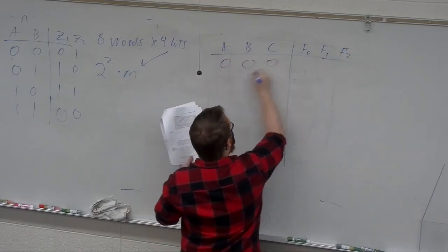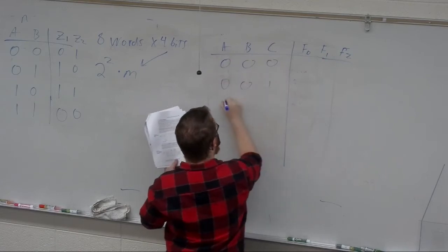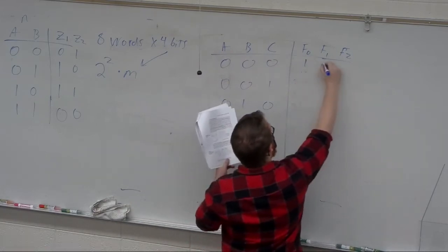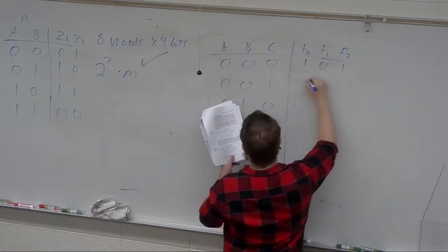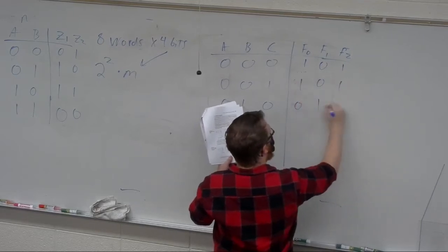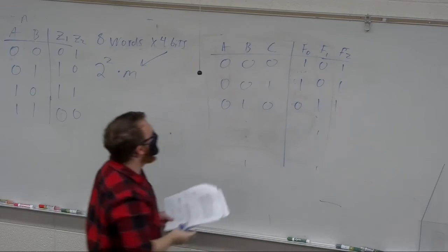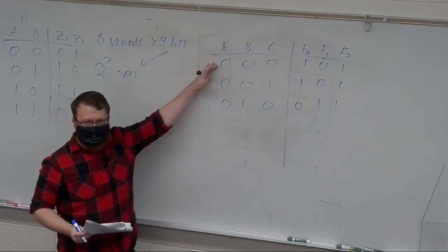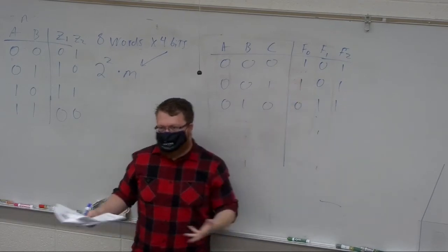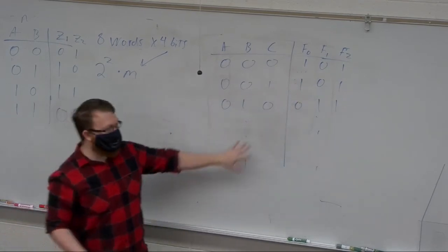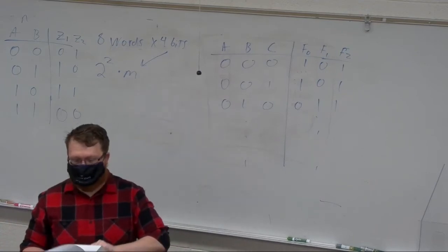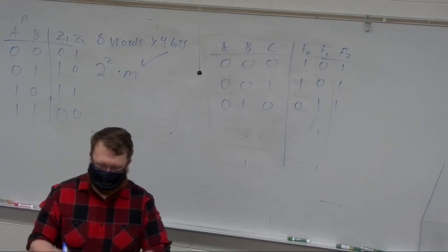And it's just saying we have a lookup table, and it's going to have some output. That you give me these inputs, get these outputs. This could be, as I said, an adder. You just have to go and figure out what is the truth table for a full adder, and now it's a full adder, as long as you program it up right on the initial programming.